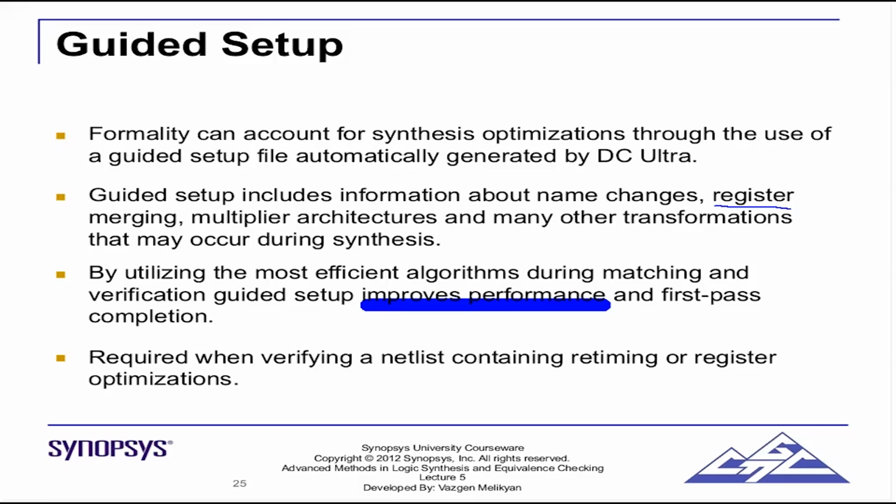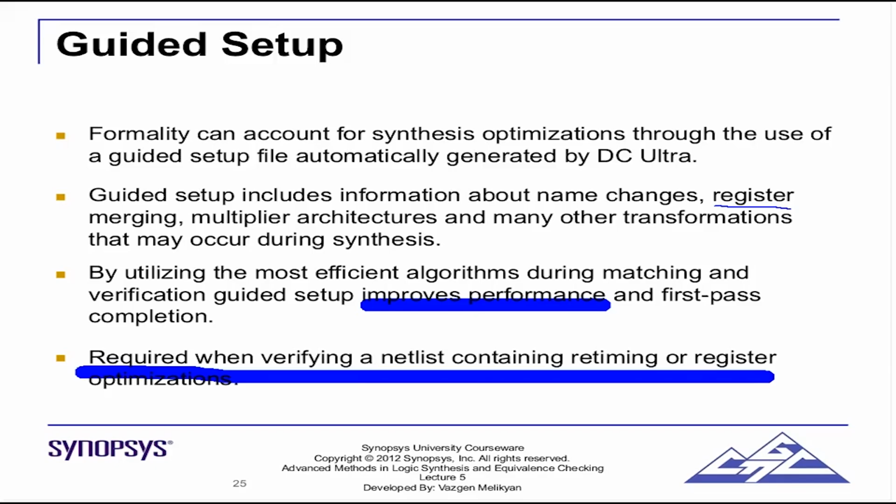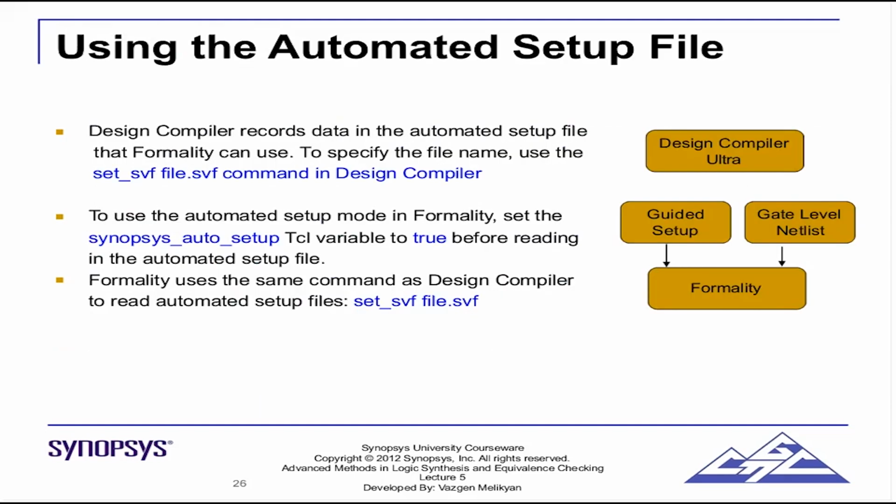That's what it says, right? Required when verifying a netlist containing retiming or register optimizations. SVF is most important when you have retiming enabled. So how do we use the automated setup file?